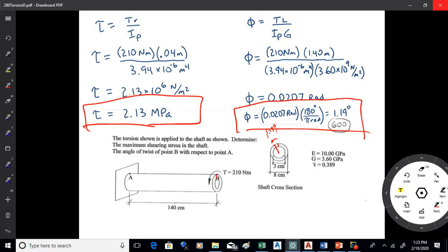Now, if there's twist in that shaft and those valves aren't opening at exactly the right moment because that shaft's a little bit twisted, you got some problems there, right? That's going to throw your whole running of the engine off because the valves aren't closing and opening when they're supposed to, okay? So there's an example of why you might be concerned with this. You couldn't tolerate too much twist in a crankshaft unless you'd already designed for it, because it'll throw essentially your timing off. The engine's not running properly. So there's an example of why you might care about that number.